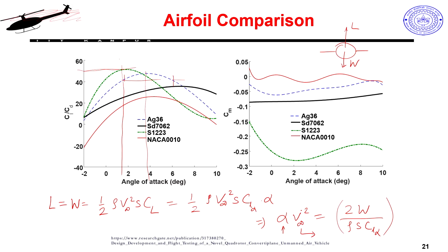Okay. So, maybe I will fly at best range speed, so that I can get there with minimum expenditure of energy and fastest. It is not like I will try to go supersonic and go super fast, because then I will burn all the energy, and I will not have enough energy left after reaching there. So, I will go to a speed which will give me the best performance in terms of best range. We will come to those things in detail. So, I will select some speed which will be on the slightly higher side. Then if I fly at higher speed, I will automatically operate at lower angle of attack.